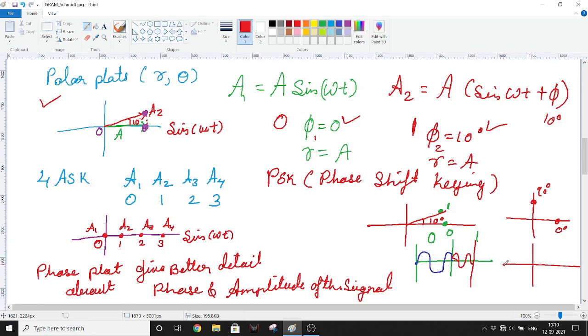At the first plot, it will be the same thing. But at the second plot, it starts at 90 degrees. Correct? And in the same way, if I happen to represent 180 degrees for symbol 1 and 0 degrees here, or I can make something like this change for 0 at 45 degrees, then for symbol 0 at 45 degrees and for symbol 1 at 180 degrees, I can have my symbol representations for 0 and for 1 in this way.